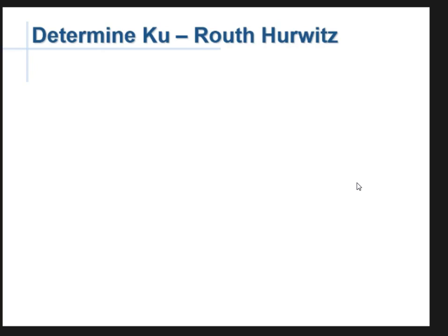So from the last row, from the S to the 0, I've got 1 plus KU is equal to 0. So one condition is that KU is equal to minus 1, but we don't usually consider negative gains. From S to the 1, I've got 9 minus (1 plus KU) over 3 is equal to 0. There should be brackets around the 1 plus KU, which when I work it out gives me KU is equal to 8.